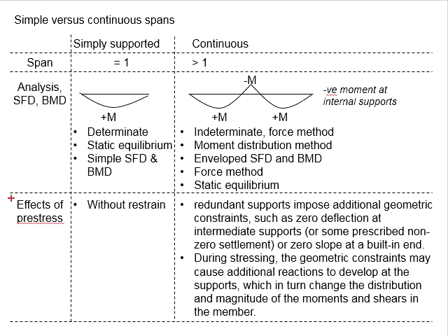When you apply the pre-stressing force, the member, which is supposed to bend outward, is now resisted by the redundant support, resisting the upward displacement of the member, and this induces additional stress in the member.